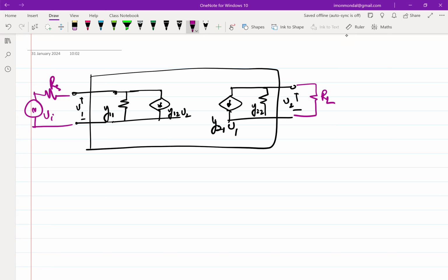By power up, I mean that the stuff that I missed in the recap was, we also established the fact that you cannot get power amplification by simply connecting an input or the output, regardless of the fact that you are using a nonlinear network. You need another power source, because simply power conservation has to hold. In principle, there is no power amplification, just that you can transfer power from somewhere to somewhere. So in this case, we saw that we need to transfer power from a DC source to an AC signal. So for that we require a DC source. So now the question is, where has the DC source gone in this model? That is his question. Can any of you give a shot at it?